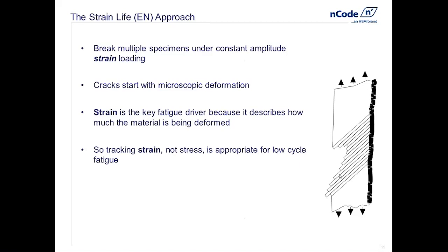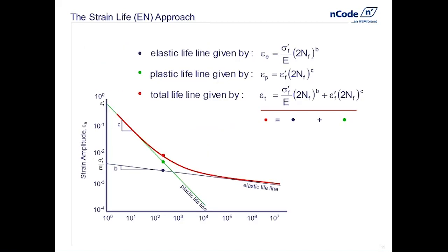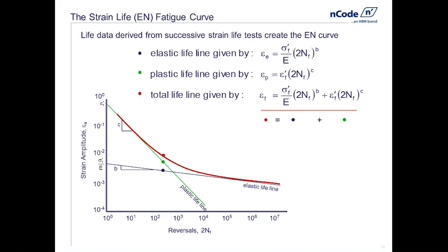You may say, stress and strain, wait a minute, I remember these. I learned that they're equivalent. There's this elastic modulus, this simple scalar that separates the two, which is true under some conditions. But as we get past yield, we have a more complex relationship between stress and strain. So don't get confused into thinking that stress and strain are simply related, because under some loading conditions that may not be true.